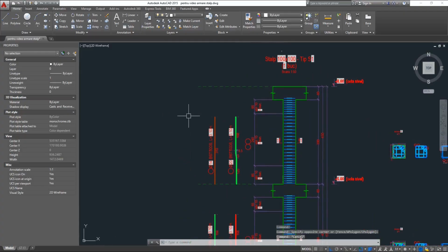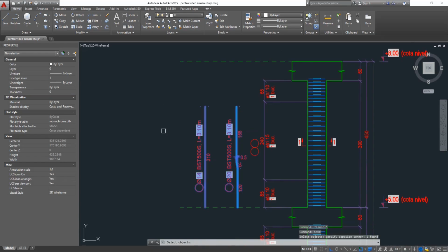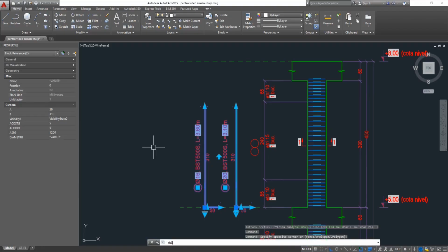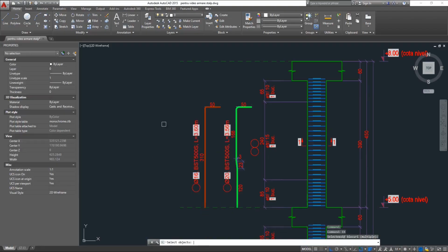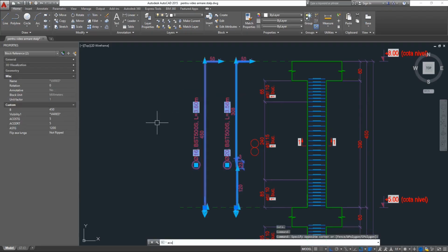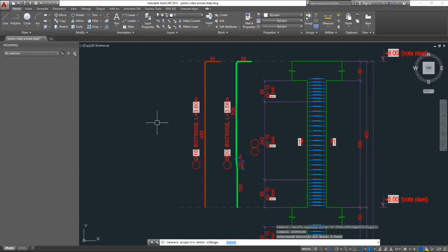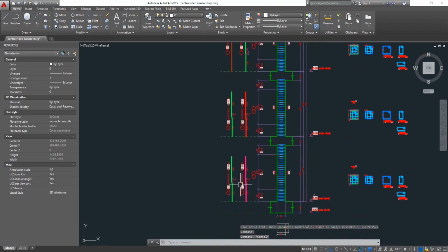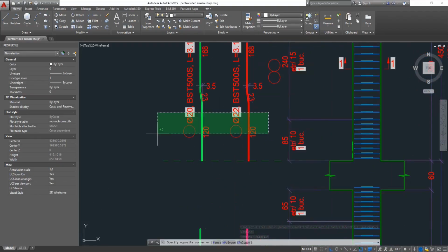Now we're going to make some adjustments, and we're going to transform these into L bars, L-shaped bars. Okay, we're going to twist them. We're going to extend them to the level, and we're going to give them a concrete coverage at the top of 5 centimeters. Okay, the next ones are going to be overlapped.